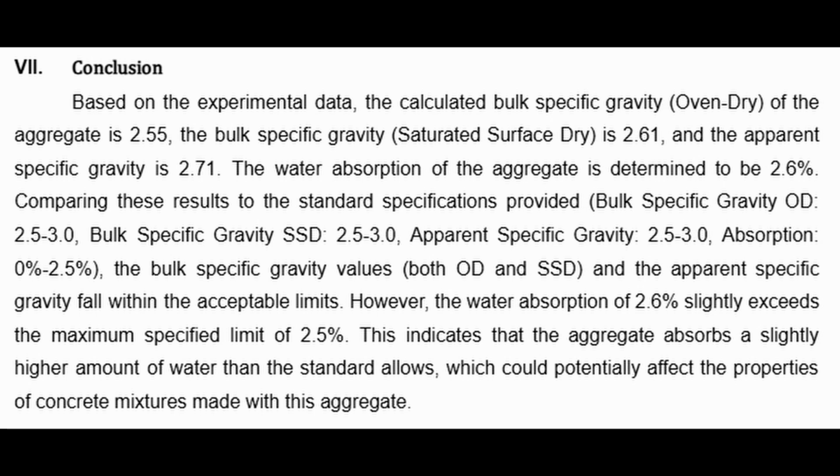the bulk specific gravity SSD is 2.61, and the apparent specific gravity is 2.71. The water absorption of the aggregate is determined to be 2.6%. Comparing these results to the standard specification provided, the bulk specific gravity values and the apparent specific gravity fall within the acceptable limits. However, the water absorption of 2.6% slightly exceeds the maximum specified limit of 2.5%. This indicates that the aggregate absorbs a slightly higher amount of water than the standard allows, which could potentially affect the properties of concrete mixtures made with this aggregate.